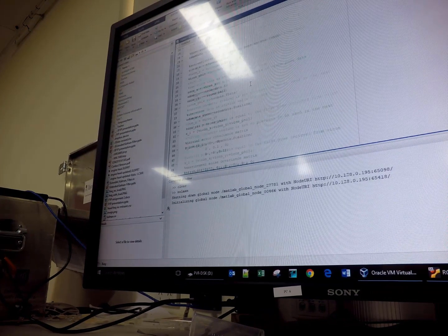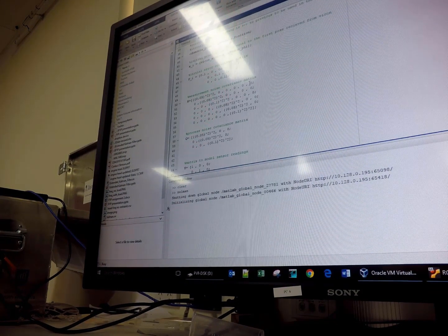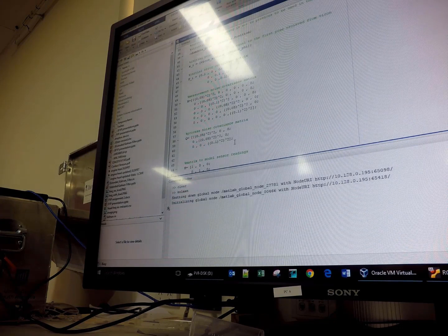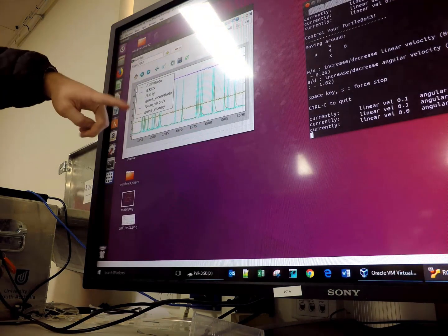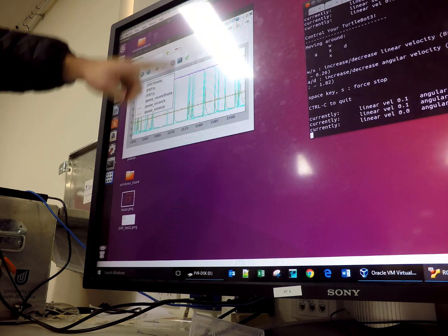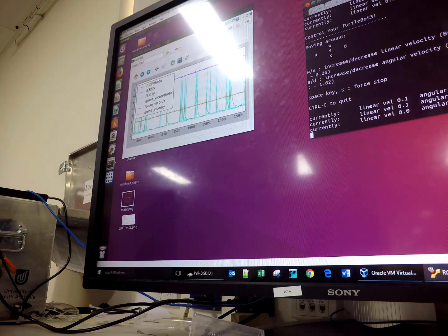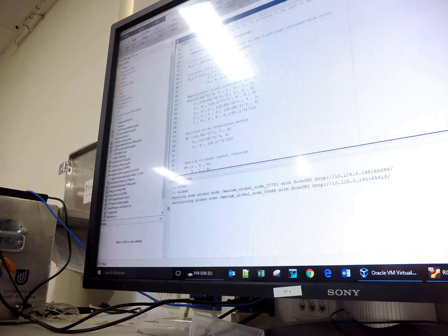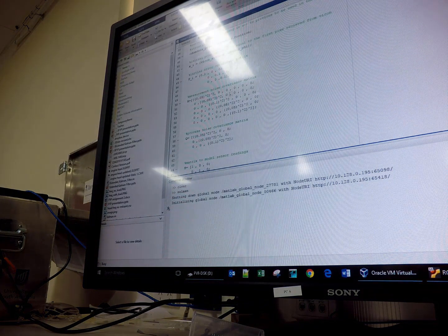So process noise is basically the error in the Vicon. I think I had it as the odometry, but it made the results really offset. So I made it the Vicon, because what was happening was the EKF and the Vicon were offset from where they should be. So I'm using the Vicon for the process noise, and then the measurement noise matrix here is basically just the Vicon and the odometry covariances.